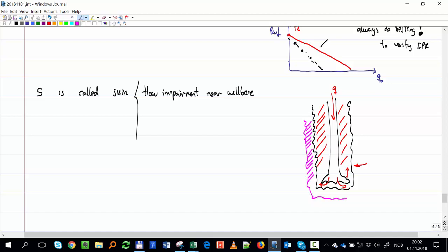So that's what we production engineers hate, okay? It's something that you have because of the drilling process. But if the mud starts to permeate and goes, not much, a few centimeters, maybe a maximum of a meter, but goes a bit far in the formation and stays there. And that mud has changed. That mud has a lot of minerals, a lot of things that are also solids, and they stay in that part very close to the wellbore.